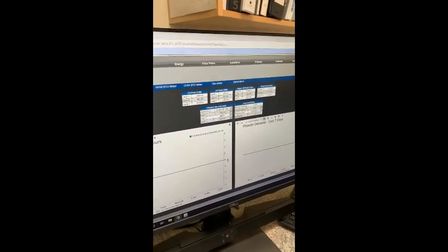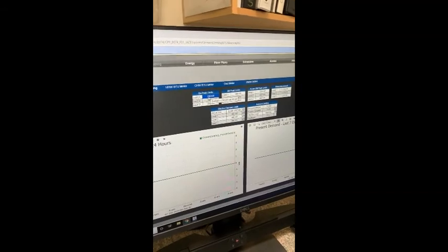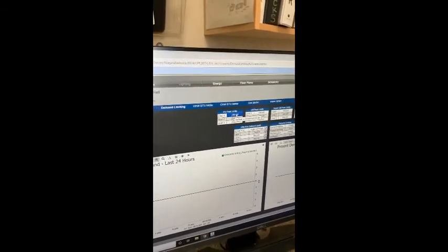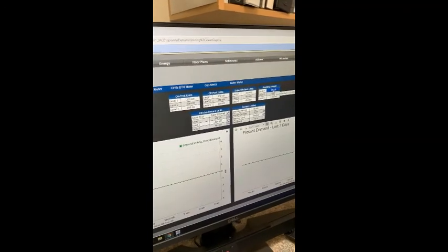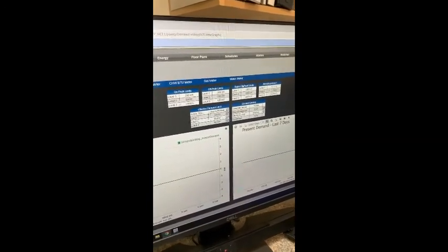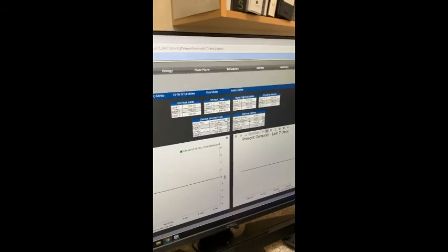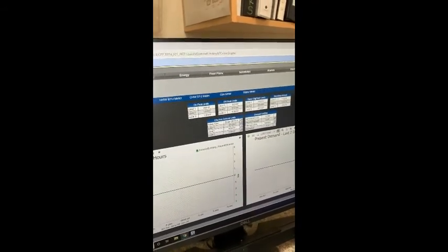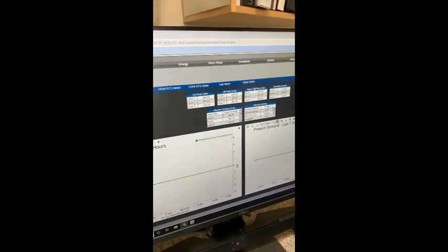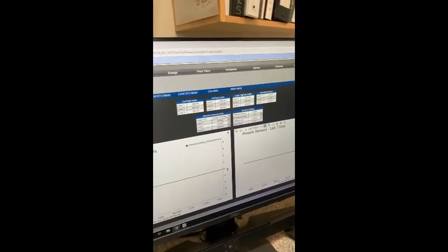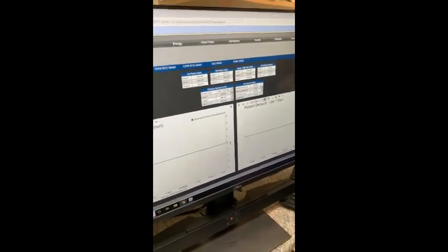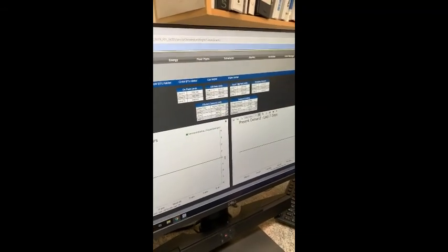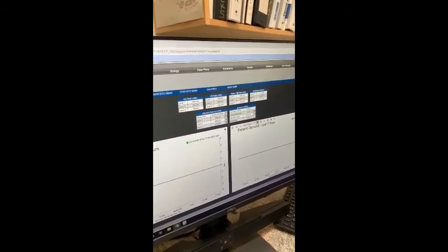So right here we can see if you're on peak time, and this building goes above 250 kilowatts, then it will set back the temperatures by 1 degree. So everything was set for their base of 72 degrees for cooling. That first level limit would then set that base to 73 automatically, and then it'll keep limiting as part of the sequence that they asked for.